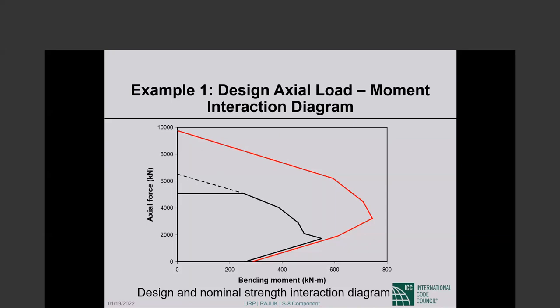You cannot do those things. If the design requires bars to be placed at the joint, bars must be placed at the joint. If bars cannot be placed, then you better change your design so that so many bars do not have to be placed in the joint. The other measures that are taken, pea gravel and super plasticizer and all of that, cost a lot of money, and they should not be required if the joint is properly designed.